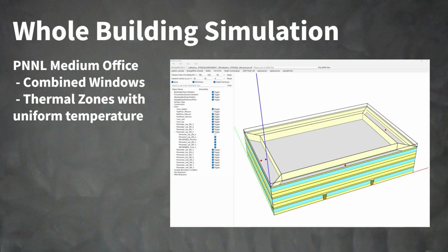You can see this is a pretty simple model of a building, so it has 4 trapezoids, one along each exterior wall, then it has a big central region. The thermal zones are set up so that these different pieces of the building, which experience significantly different loads, are all modeled correctly. So if the sun is shining in on one side of the building, it's going to have a significant load from the sunlight going in, and then maybe on the other side it's going to have less, and the other 2 sides might get some sun, and so they'll have a different load.